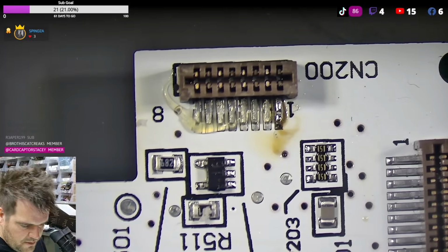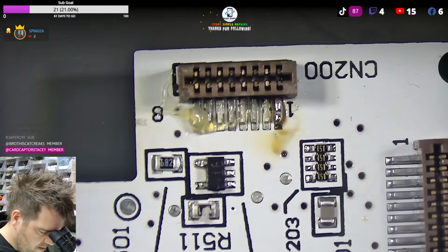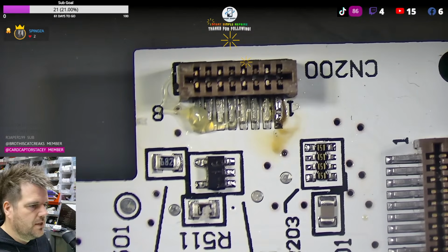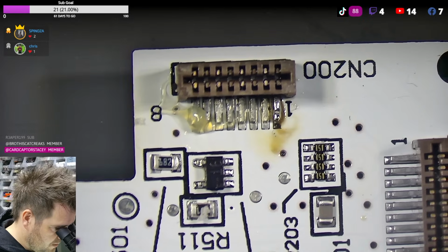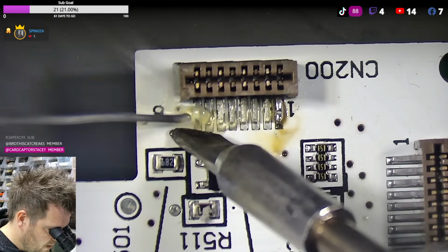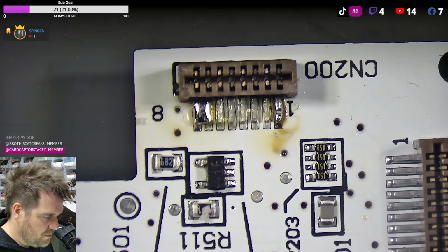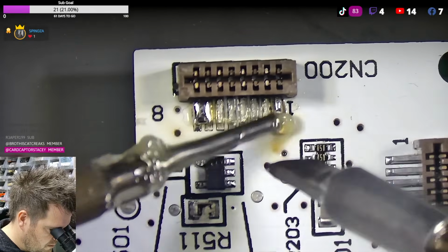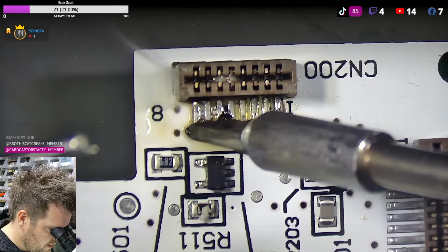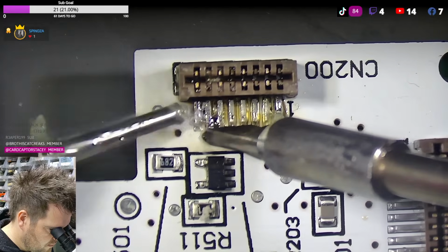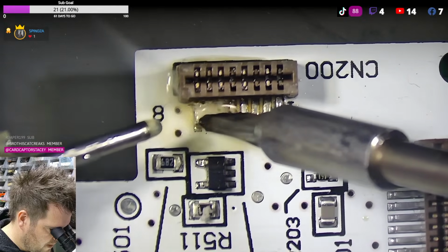And now all we need to do is, if you're doing an iron, I'll go from the other side, tack this pin in, and then I'll probably just drag solder down. We'll go and tack one more in down here. And you can see there now what it wants to do is just bridge. That's perfectly fine. All we do is plenty of flux. Go down slowly with your iron, a lot slower than you think. And the heat will transfer through. And you'll normally just drag that off.